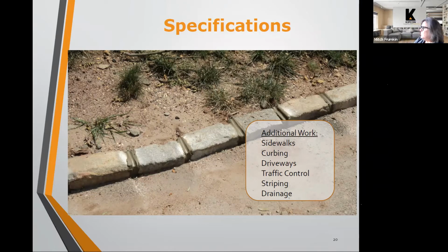When you have really beat up pavement with a lot of cracks, when it rains, a lot of that rain goes into those cracks, so you don't see a lot of surface water. Once you get brand new pavement, one of the complaints that we receive is that now people see water flowing in the gutters, and it's meant to be that way. Once you put down new pavement, you have a lovely impervious surface, and so when it rains, that water runs off instead of running into the cracks of the pavement.